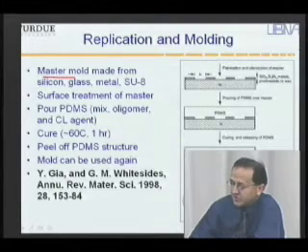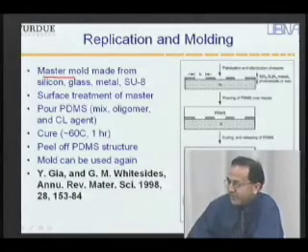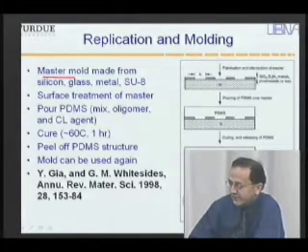And here is the cross-sectional flow picture, which is detailed in a review by Whitesides. So here's a silicon with a certain material as a master. PDMS is poured and cured, and then the PDMS can simply be peeled off and released, and the master can be used again.